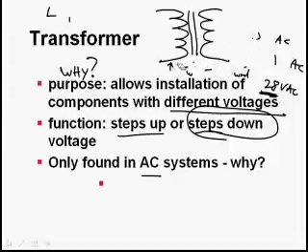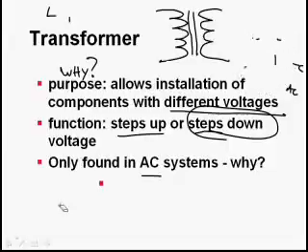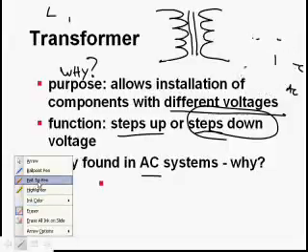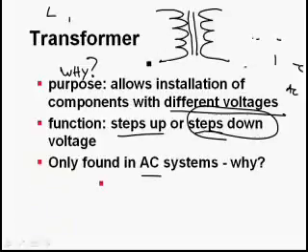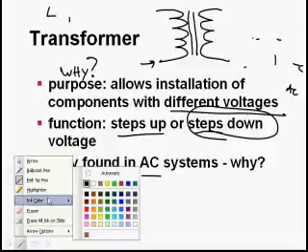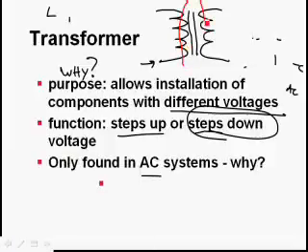Electromagnetic induction? I thought that was only for generators and alternators. Well, if you had that thought, I'm glad you're thinking. But you can have electromagnetic induction other ways. Let's say we run electricity through this coil. It's going to generate lines of flux. And as they're forming, they're going to start from the center of the wire and move outward. So these lines of flux will actually cross these other wires.